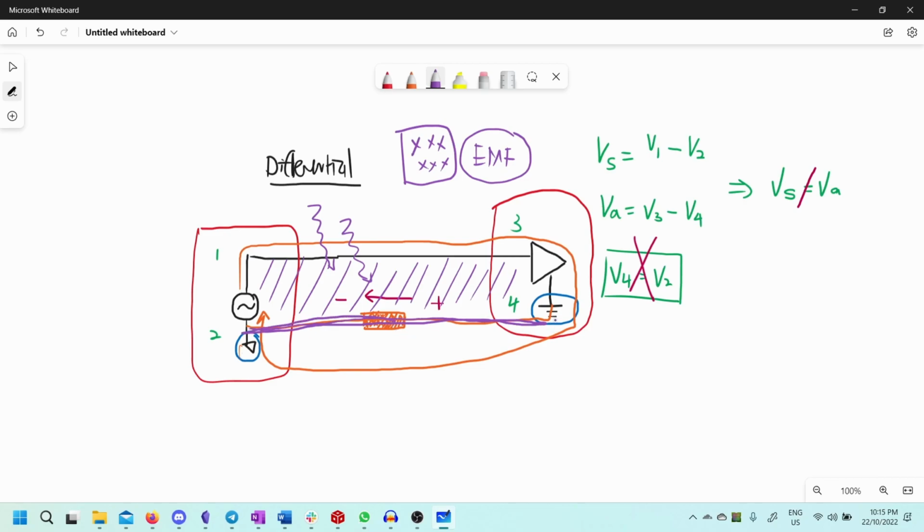So there is going to be a current that flows through this ground connection just by courtesy of whatever cosmic rays or antenna transmitters or your phone that is close by. Changing magnetic fields induce a voltage across this ground node. And this voltage is essentially going to be noise because it's not coming from this. It's external. So how do we solve this?